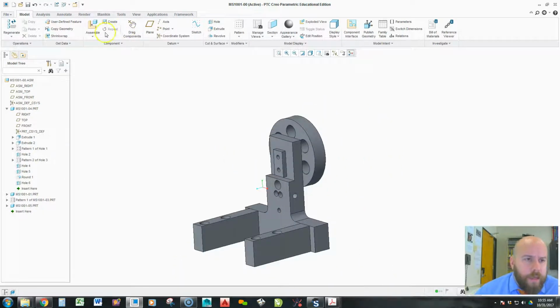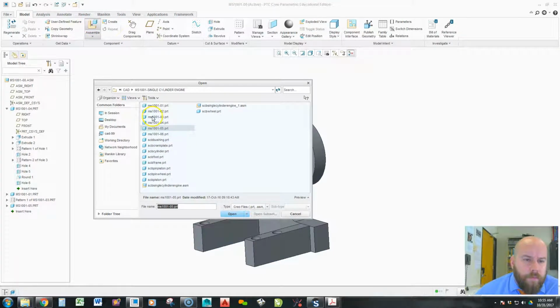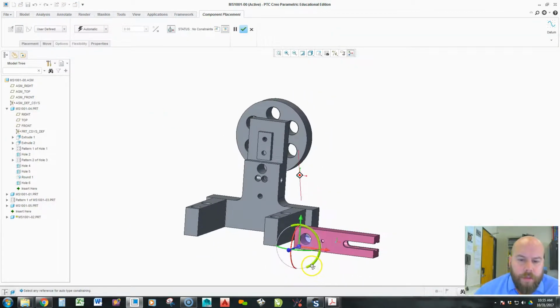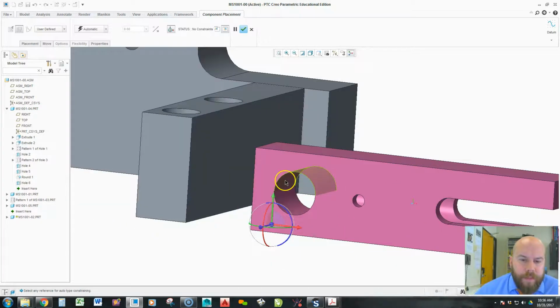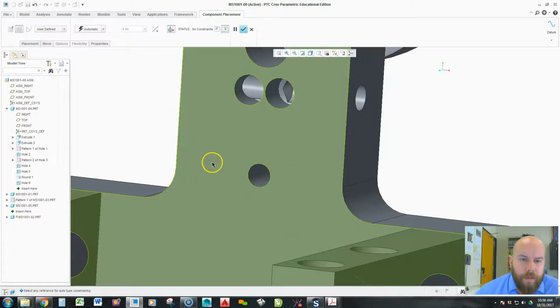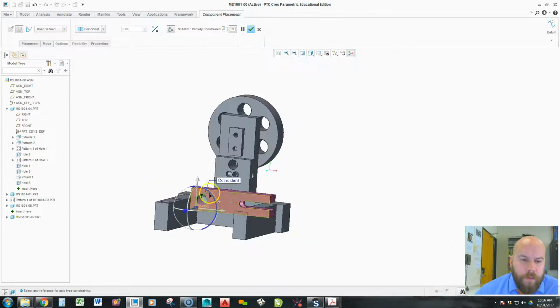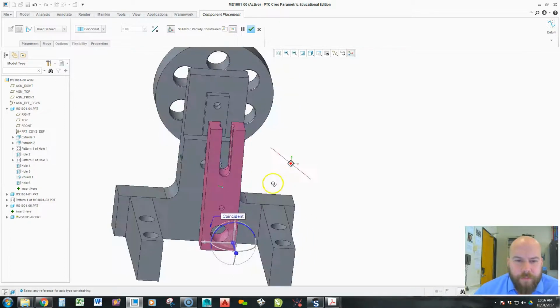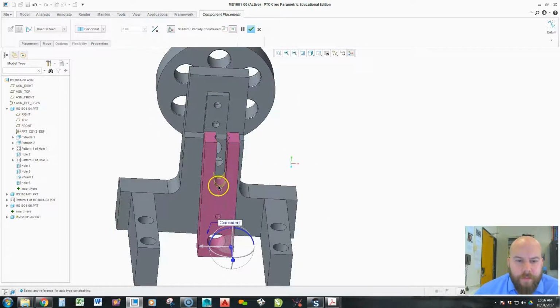And the next thing I need to do is I need to assemble part number 2, okay, which is my cylinder. All right, so the way my cylinder works is this hole lines up with this threaded hole. Okay, and that's where it rotates around. I have a little bushing I'm going to assemble that rotates around. Okay, now the other thing that matters here is that this right here rotates with the bottom pin here, because there's a little piston that moves around.